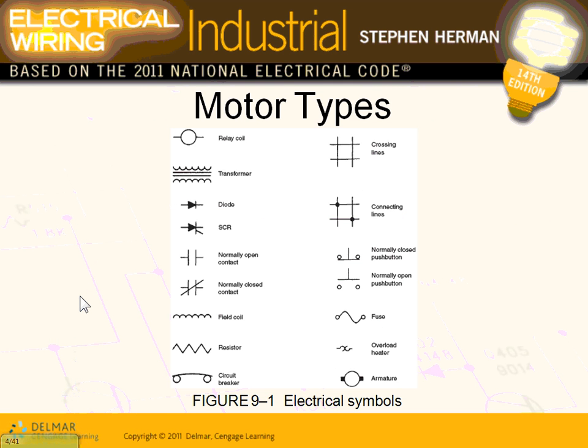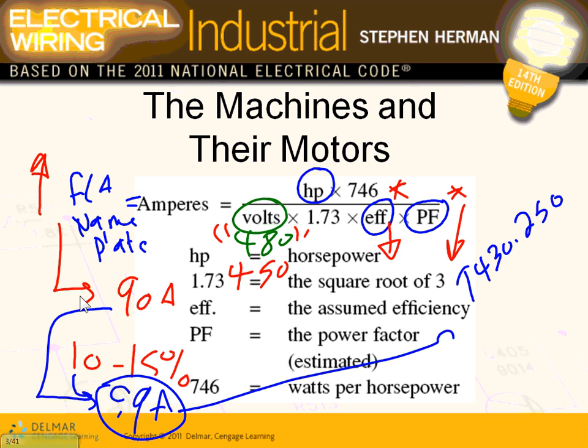Now, if you're managing a plant, guys, knowing that your power factor is down is a big deal. But if I can get you to understand, improving the power factor and the efficiency and having a good voltage, no voltage drop, will improve the full load current. Everybody got that one? That's all I want to get. That's why we always keep hammering guys into low voltage drop. We don't want a lot of voltage drop. We want the efficiency of the motor to be good, and we want the power factor correction, like we're going to do in the coming chapter.